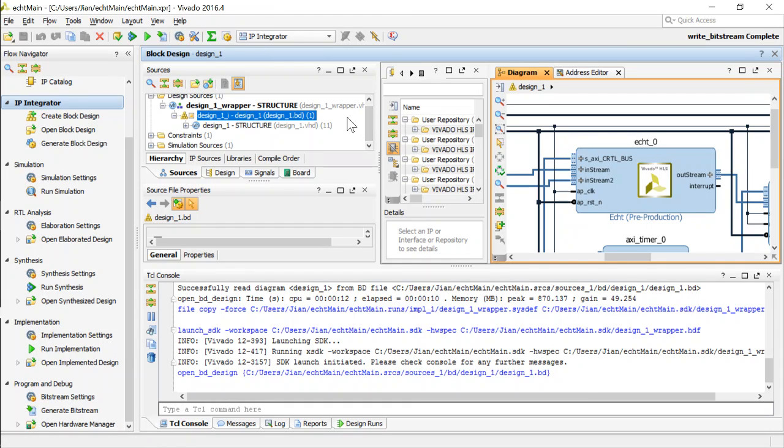So in this video, I'd just like to show you how to go through the entire synthesis process. So the next thing you have to do after you have your design in place with all the files I've given you is validate the design to make sure that there are no obvious errors like a clock signal not being driven. So after you validate the design and you verify that it's correct, there's essentially 3 more steps.